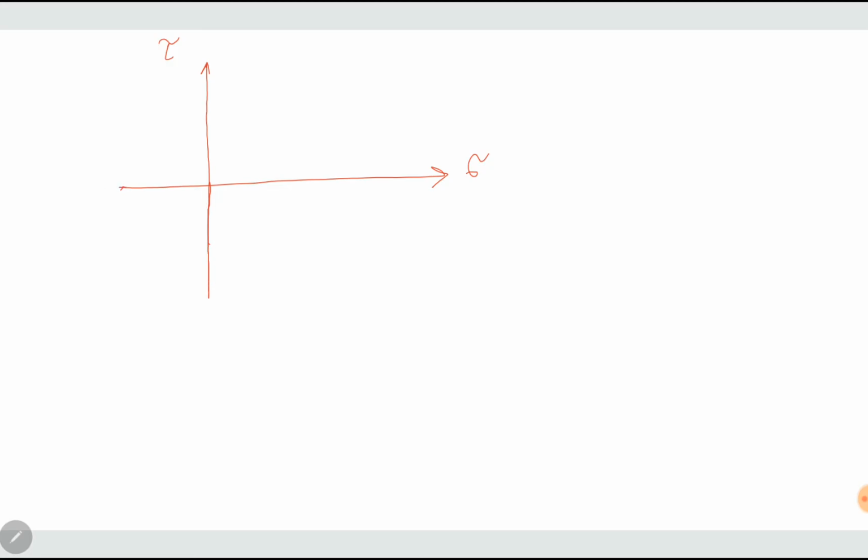On a graph paper, first you have to take a scale: how many centimeters or millimeters are equal to how many megapascals. After that, sigma x, sigma y and tau xy are given. So we have to plot point x as sigma x, minus tau xy, and point y as sigma y, plus tau xy. Once you denote these 2 points, the first step is to identify x and y points.